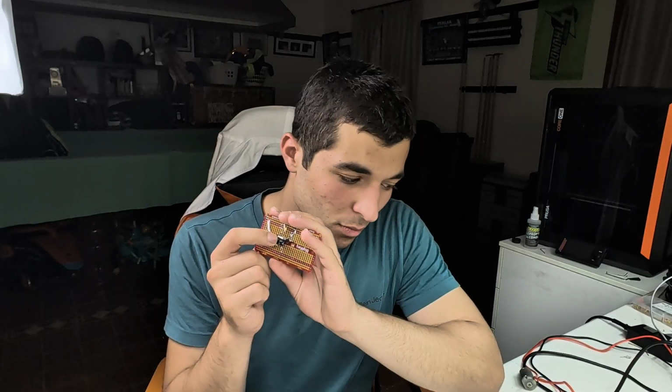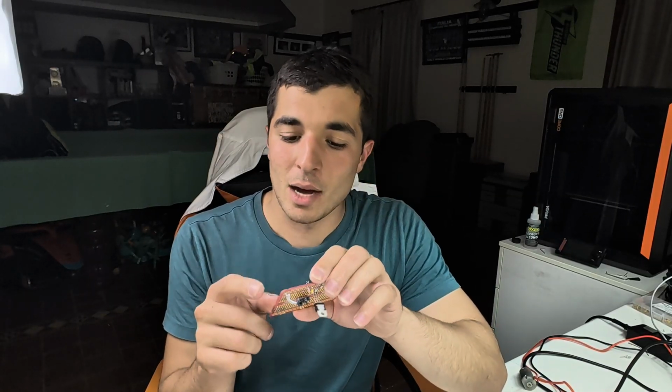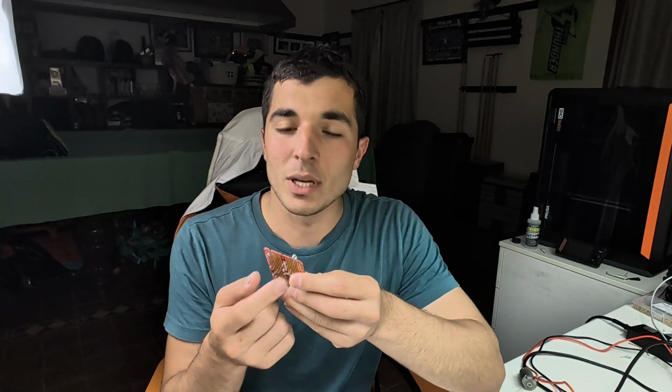So where was I going with that? I put it in and one of the pins wasn't connected. It made the boost converter seem like it wasn't working. I was measuring output voltage, and instead of 5 volts I was getting 4.7. That might be because I'm using a Schottky diode, so it might have a lower threshold, but that looked like the diode taking up the voltage.